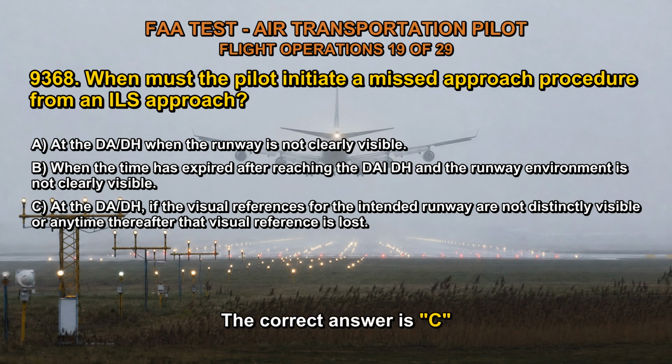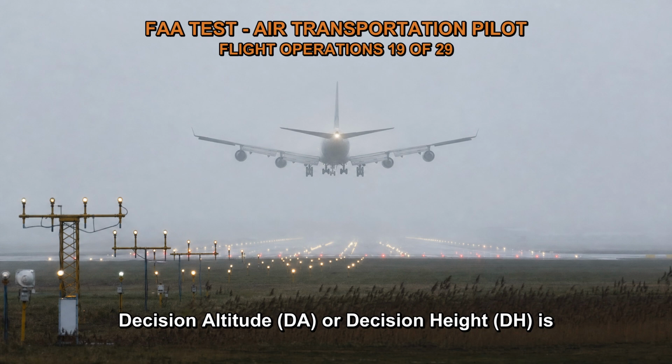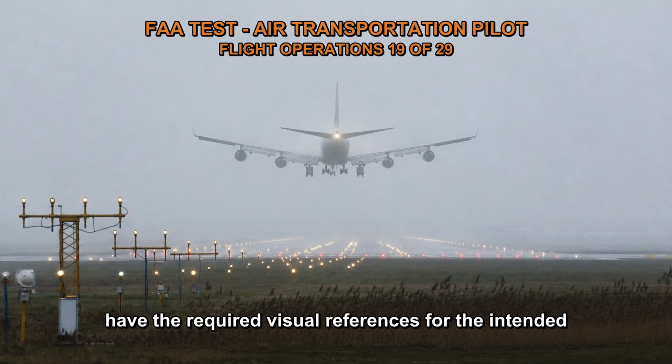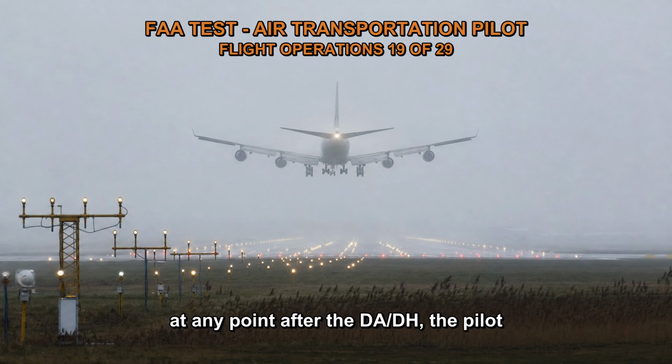The correct answer is C. During an instrument landing system (ILS) approach, the decision altitude (DA) or decision height (DH) is the point at which the pilot must make a decision to either continue the approach or initiate a missed approach. If, at the DA/DH, the pilot does not have the required visual references for the intended runway, or if those visual references are lost at any point after the DA/DH, the pilot must initiate a missed approach procedure.